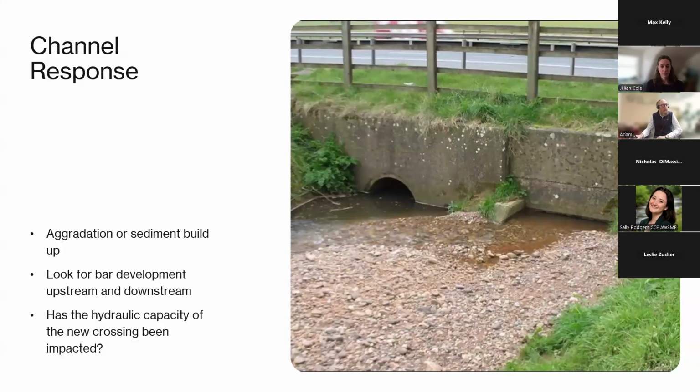Another potential channel response related to the sediment transport side of the geomorphic assessment would be any aggradation or sediment buildup. So post-construction, are you seeing bar formation, either development upstream or downstream or through the structure, or just changes in how the sediment is moving through the project reach? Jillian had mentioned that it's typically best practice to span the entire channel in those situations where you are going to have a pier in the active channel. That can oftentimes lead to not just accumulation or trapping of wood and other debris, but also sediment. So it's important to look at how those bars might develop over time.